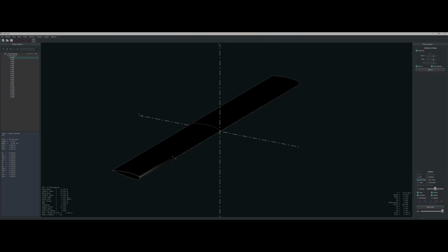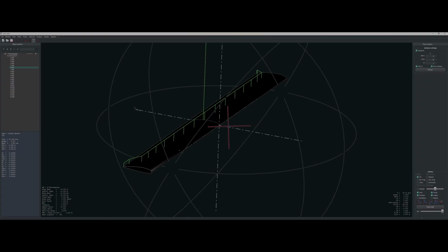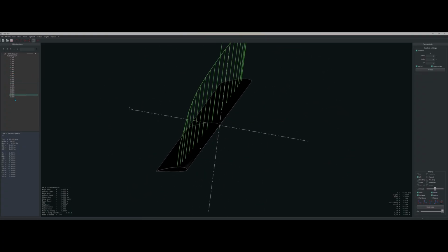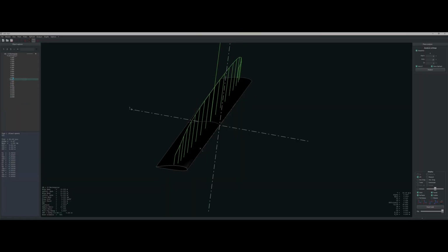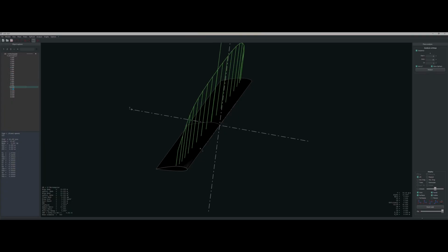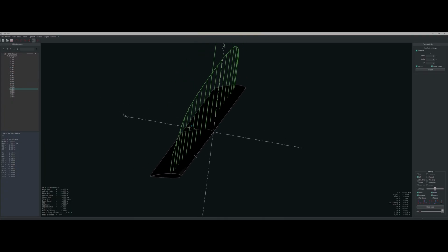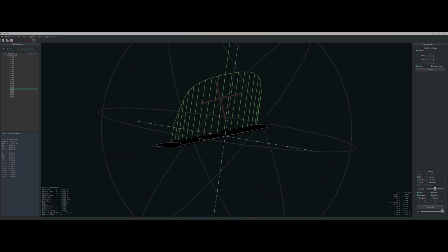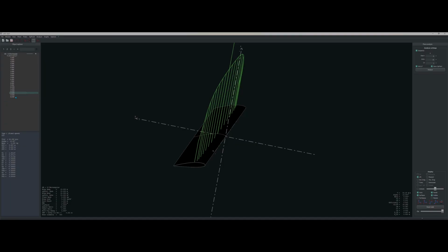You can see our lift here. This is at -5 degrees, so it's lifting down. If we go to 0, you see it's lifting up. And it's showing like that. This is a behavior that's pretty typical. Of course, you see as there are higher angles of attack, the higher the lift, and also you can see our center of pressure moving up at higher angles of attack. So this looks good.